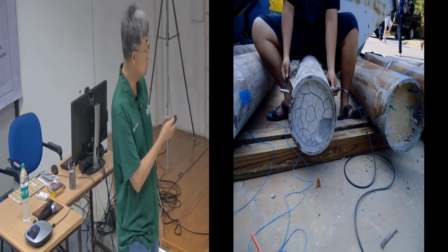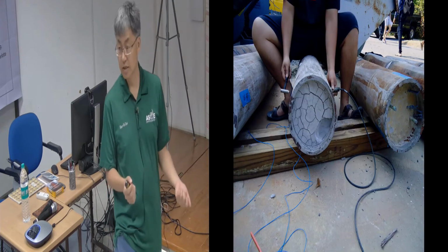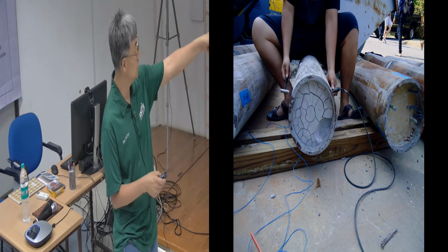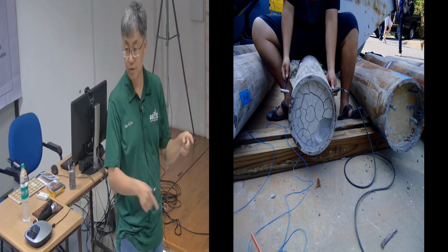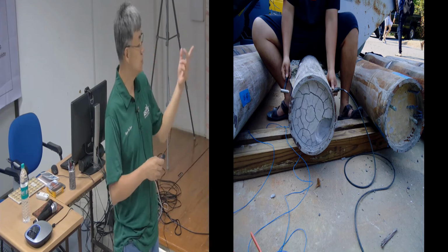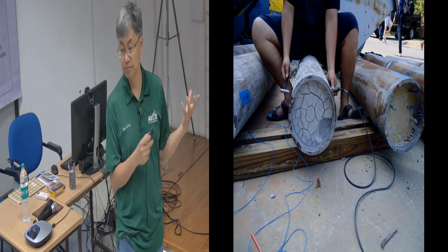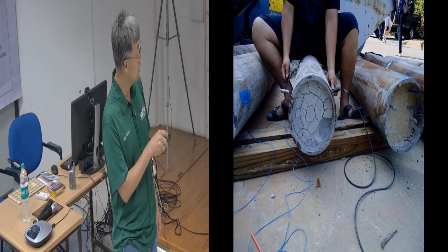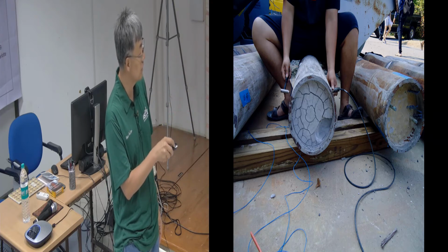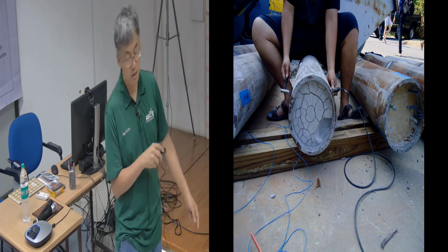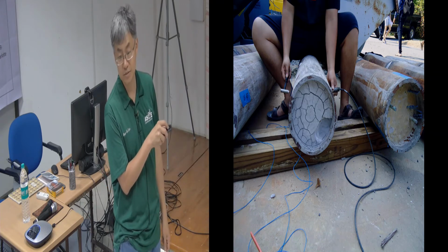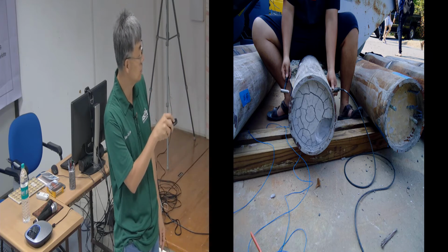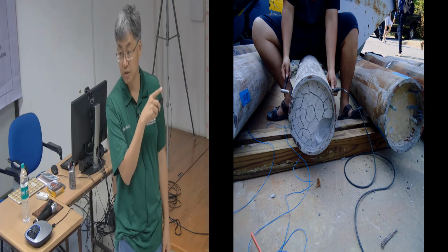We use a similar technique to do an impact echo kind of test. This is a concrete cylinder cast with steel casings. This is not for any particular case application, but you can see we were able to tell the results of a poor concrete and a good concrete case. The poor concrete was already load tested, which is why it already cracked. So using this technique, we were able to tell the difference in the wave propagation in the cylinder.